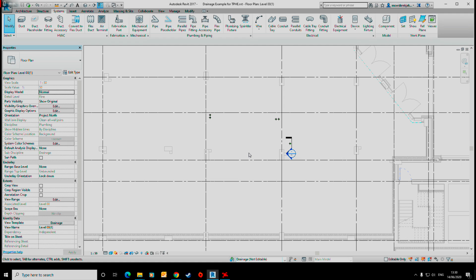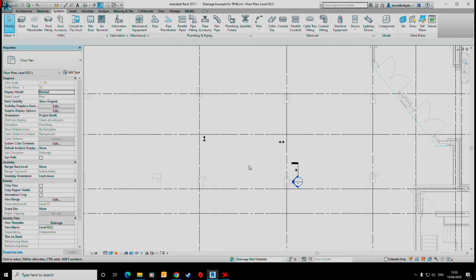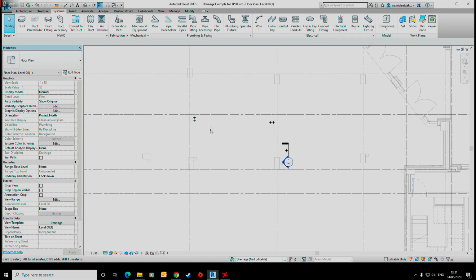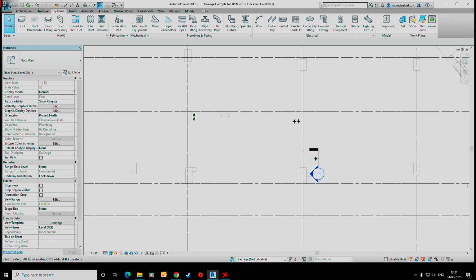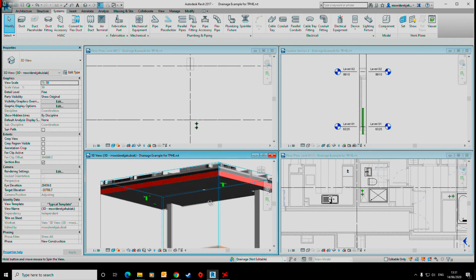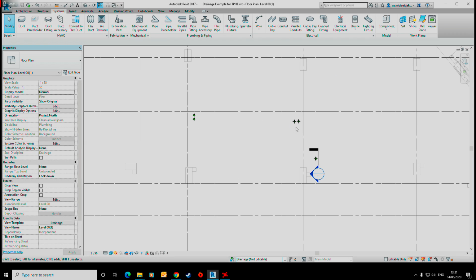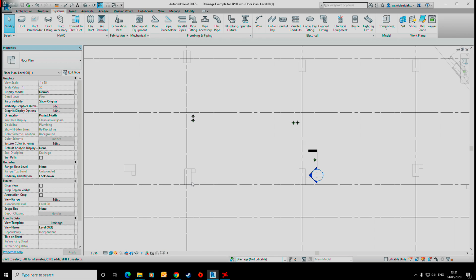This is the ground floor of the building, where we have our retail unit, our future shop, and we have to offset, or suspend, this drainage. Obviously this drainage is dropping to high level within that shop, and we have to transfer that drainage at high level to a point where it drops to below slab drainage. In our case, this is going to be a column.